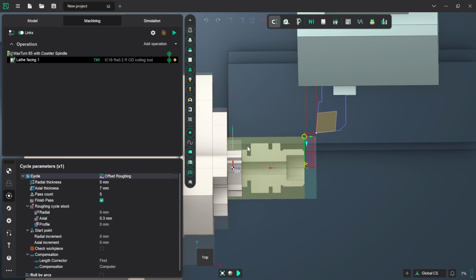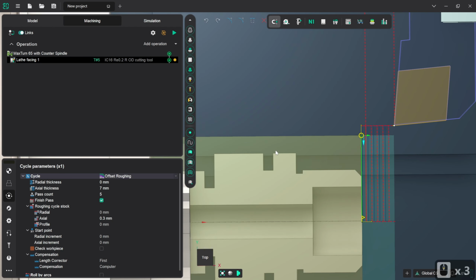However, what I'm going to do at this stage is in fact do a grooving operation at this point to operate some relief for the roughing pass, because if you think about it, if we use this tool here and it comes up to this point, due to the way that it wants to default leading in and out, it's going to be cutting quite heavily into the leftover material here. So we want to make sure that's clean and easy and doesn't require any extra work.